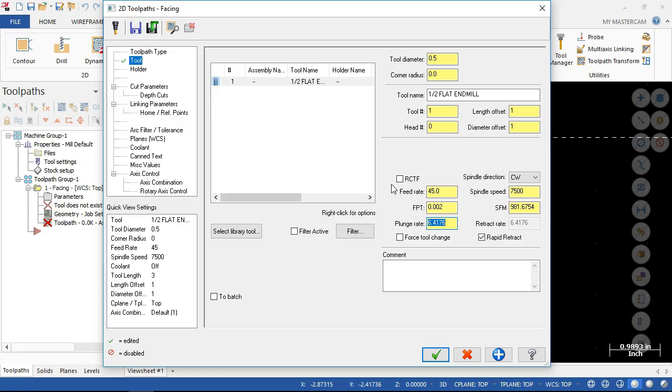All right, so I'll give you an example. The tooling plate that I prepped, I put on the table. I touched off the first part to the table and forgot to raise it up to my tool offset. And I said, that's making a strange sound. And about the time I looked down and hit the feed hold, it had moved about 8 inches, half-inch wide, 3/8 of an inch deep into my brand new tooling plate. So I always know which side of the tooling plate faces because I put the gouge there. All right, so 45 inches a minute is, don't blink, because it is still moving pretty good.